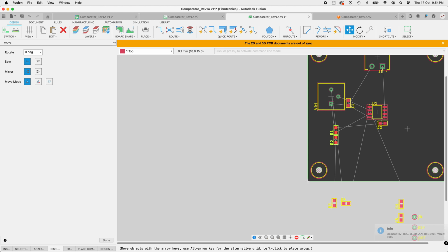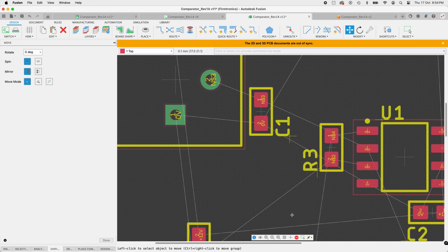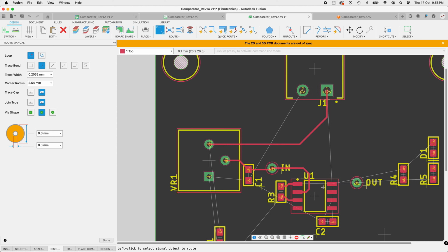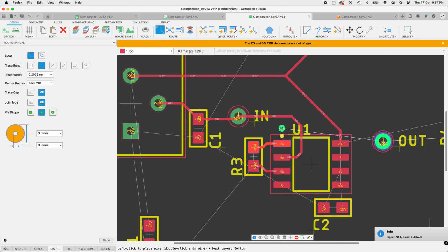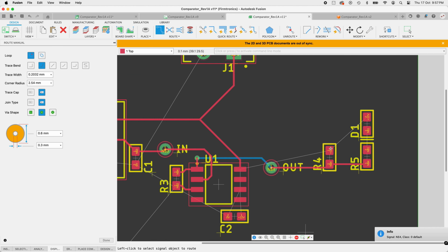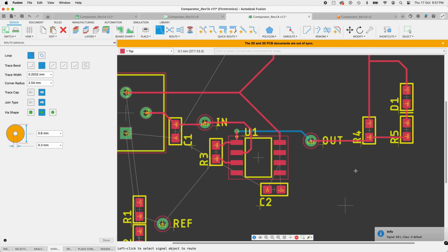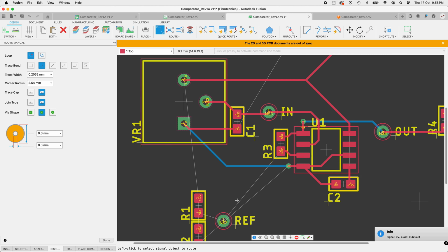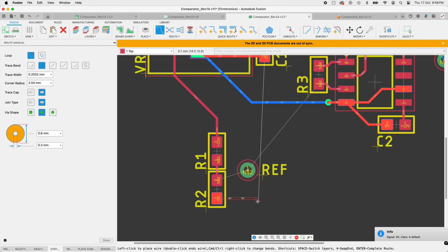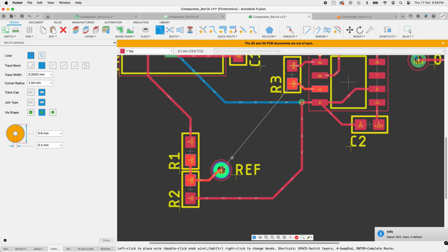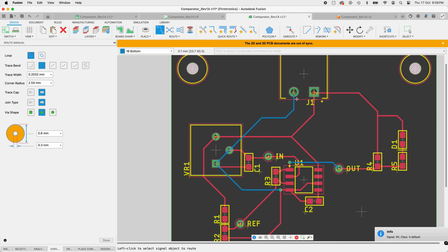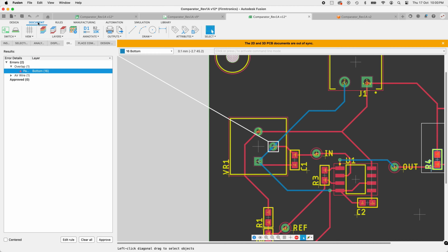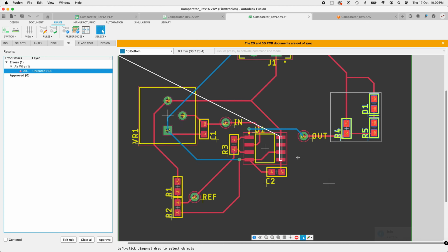We will tie the second comparator unused inputs to ground as per the datasheet recommendation, as the LM393 used in the design is a dual version by definition. Finally, we will connect the input to a triangle wave and verify on an oscilloscope that the output transitions at the high and low input thresholds. We will also observe the non-inverting input voltage, which will show us an easy way to visually verify the 1 volt hysteresis band due to the switching in of the feedback resistor, which is dependent on the output state.